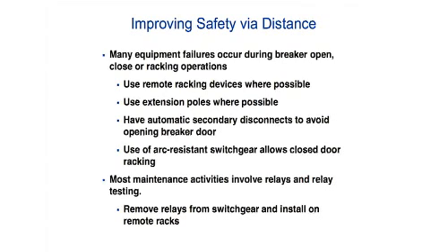The next one is, do specify automatic secondary disconnects, because we've seen some customers that are saying, maybe I ought to be looking at an IEC design. Just understand that there are things within ANSI that truly do prove to be, over many decades, time-proven logic in terms of what created the safety to begin with. This is the reason why in the European world they had the problem. And actually here in the US we didn't have the problem, because we always had metal barriers in between the frames.